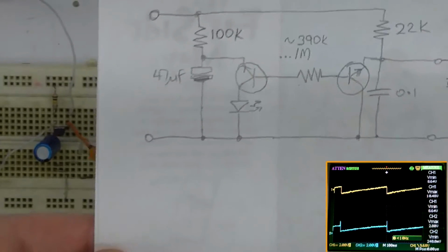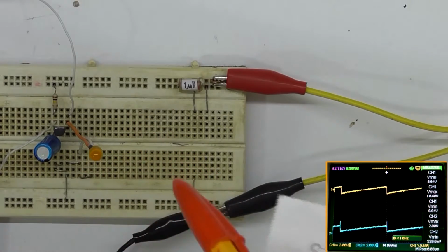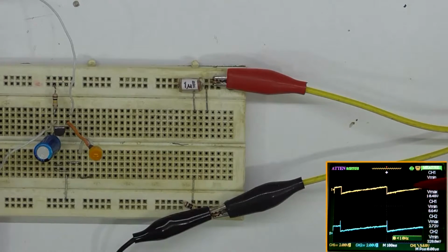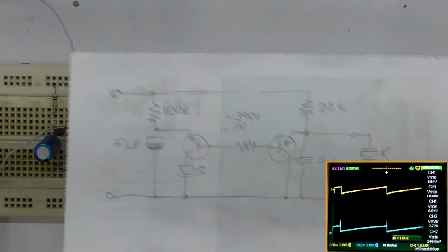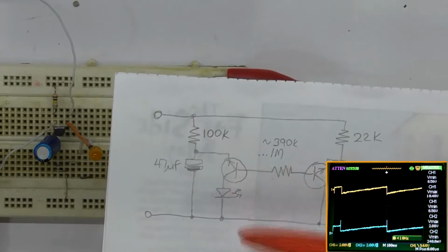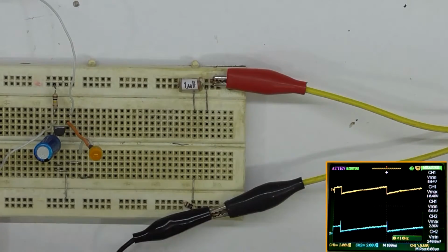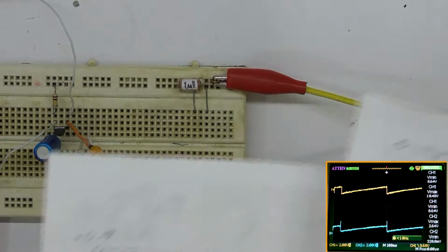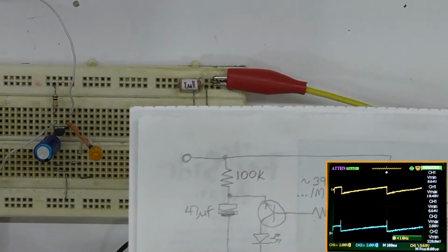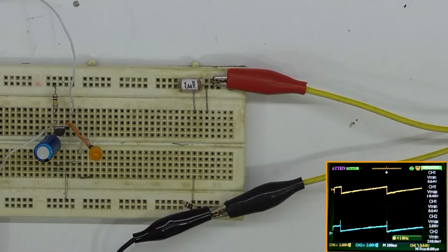Okay, so going into examining this circuit, I've pulled everything out and I've only got the low frequency side. I've got channel 1, which is the yellow trace, hooked up to the emitter, and channel 2 on the collector just above the LED, using a different LED this time. I don't know whether that's going to make any difference to its visibility, because it was a timing issue. So let's look at the oscilloscope.